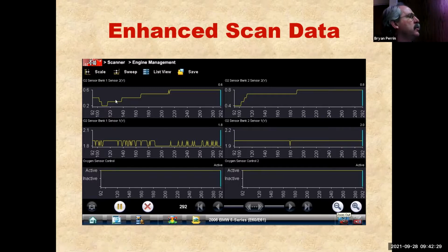My bank 1 rear sensor is at 600 millivolts. My bank 2 rear sensor is at 800 millivolts. So here I have a situation where bank 1 is richer before the converter, but leaner after the converter compared to bank 2. So now I'm down to the same possibilities. We've been here before. This is like our Nissan with a different code, right? I'm seeing the same pattern I've seen.